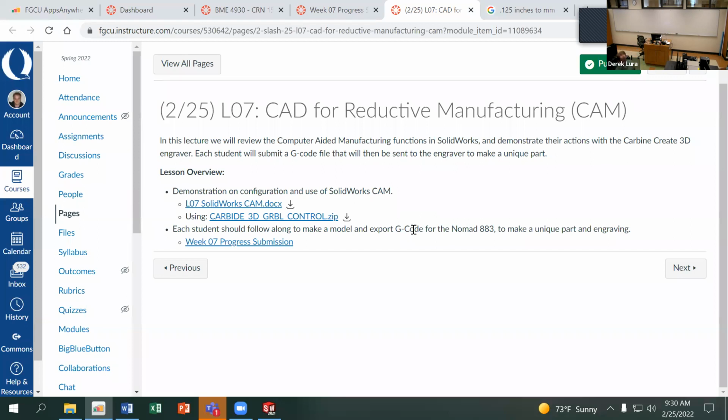If you click on this little button right there, that is the error between the actual part and the machined piece. The reason it's overcutting, it's cutting that out. I don't know why. If you go back to your operations, look at the bottom. You still have an operation from your previous run through. So if you just find the one that is that part and suppress or delete it, it's fine.